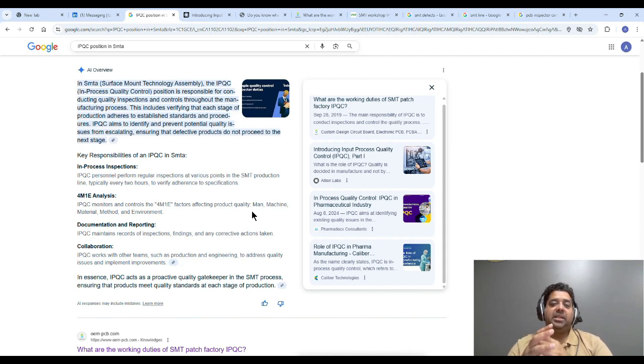But as an SMT engineer, you get to choose, or you would have to choose, which supplier you want to use, because different suppliers make solder paste differently, and some suppliers have very unique solder paste which tackle very unique problems. So you need to figure out materials, you need to figure out what solder paste you're using, you need to figure out who's going to make your stencils. Okay, solder paste, stencil.